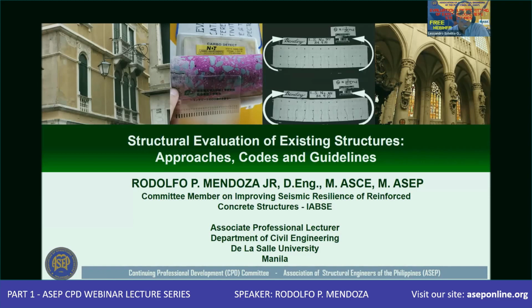Okay, yeah, that's right. In the evaluation of an engineering structure, is it not required to do NDT? I think this means non-destructive tests, together with the theoretical calculation evaluation of the strength. Yes, as I mentioned, structural evaluation can actually consist of a structural assessment or structural analysis, or both. And in the structural assessment part, it may include determination of the in-place strength of materials in order for us to perform a structural analysis.